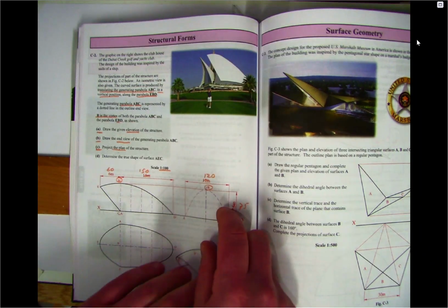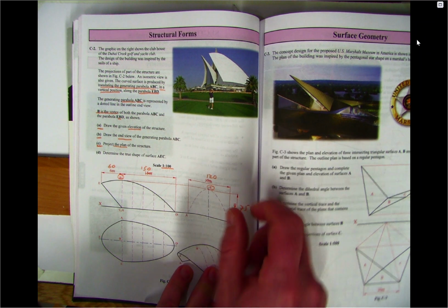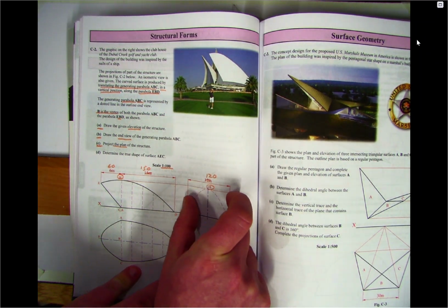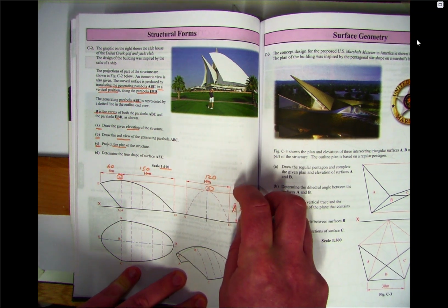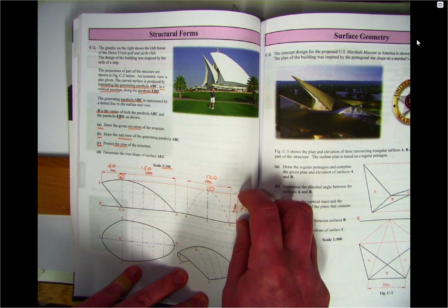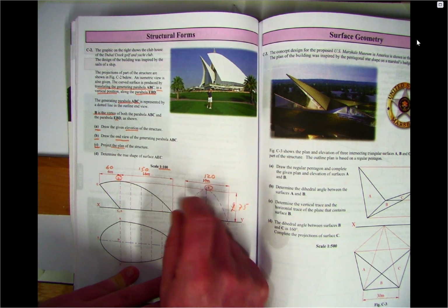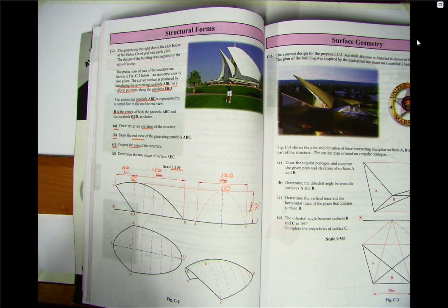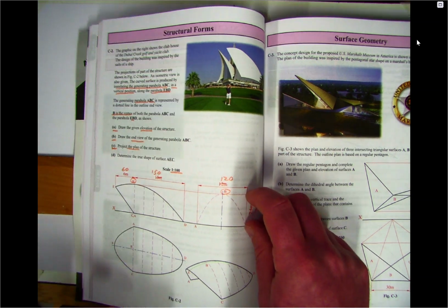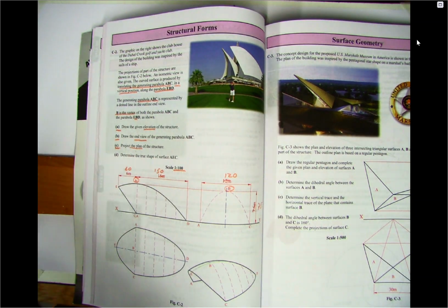Now we could use the division line method for these, and as I said before in some of my videos, I would typically do that for an exam question just to make sure the examiners know that I can use it. However, this divides easily by 5, and this being 60 divides easily by 5. And the same with these two measurements. So I'm not going to bother doing it for today's video, but if it was an exam question, I would at least do it on one corner, just in case part of the marking scheme was to show that I was able to use the division line method.